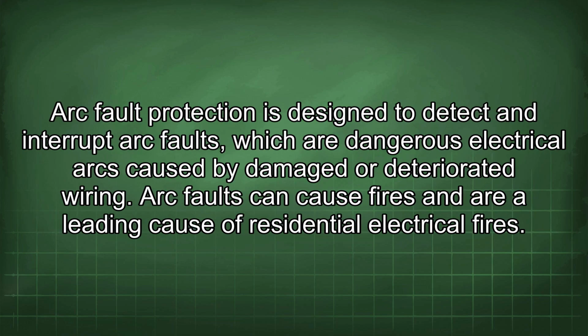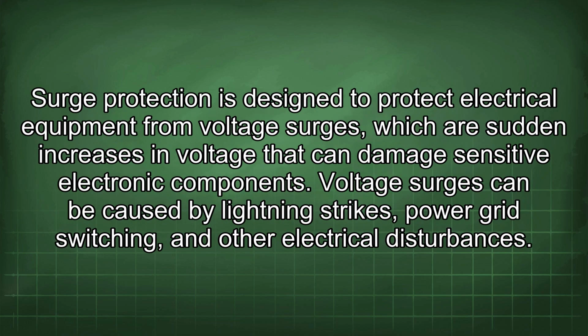Arc fault protection is designed to detect and interrupt arc faults, which are dangerous electrical arcs caused by damaged or deteriorated wiring. Arc faults can cause fires and are a leading cause of residential electrical fires. Surge protection is designed to protect electrical equipment from voltage surges, which are sudden increases in voltage that can damage sensitive electronic components. Voltage surges can be caused by lightning strikes, power grid switching, and other electrical disturbances.